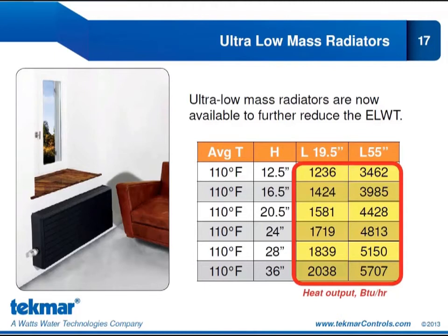Now, on the chart, we have shown information from one of the manufacturers of ultra-low mass radiators, and you can see we're assuming an average temperature of 110 degrees Fahrenheit. Now, this would be the lowest water temperature for this particular manufacturer, but I have seen others that have starting water temperatures as low as 95 degrees Fahrenheit.